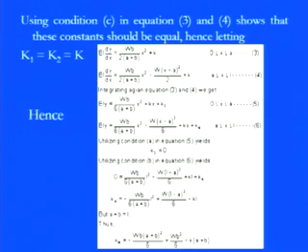So EI into y for the AB portion, that means the deflection condition, is WB by 6 into A plus B into x cube plus kx plus k3. Now we have the new term k3 because of the integration. Then for the BC portion, EI into y is equal to WB by 6 into A plus B into x cube, minus W into x minus A whole cube divided by 6, plus kx plus k4.